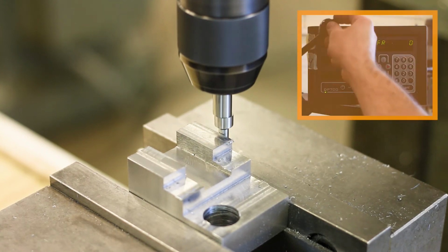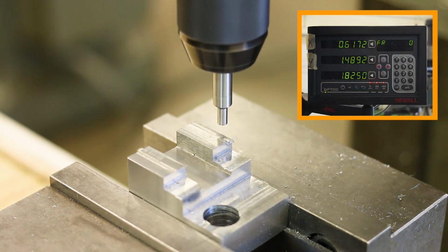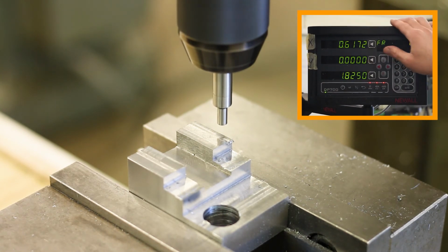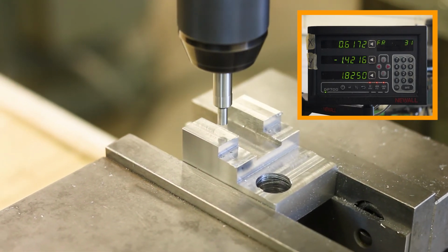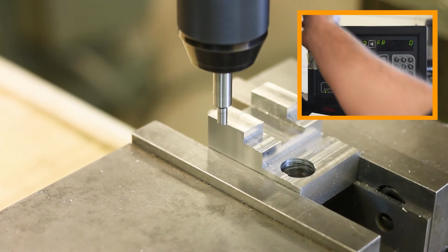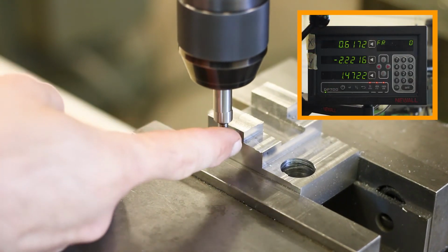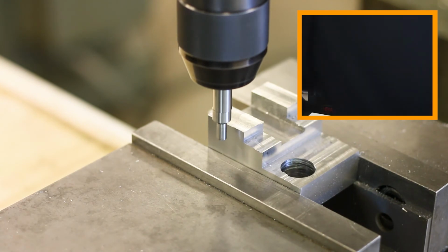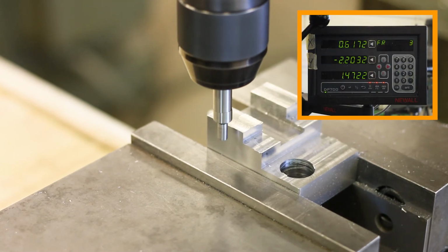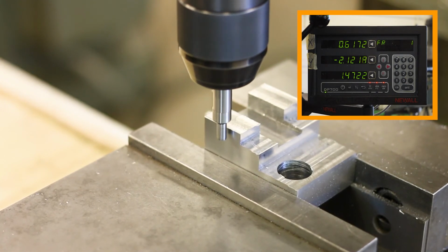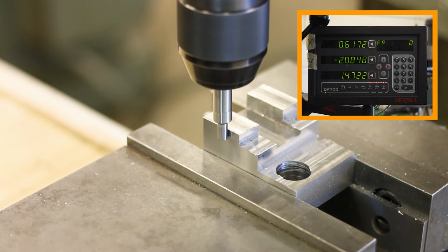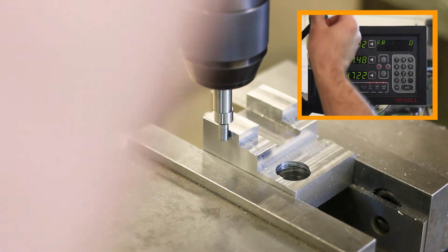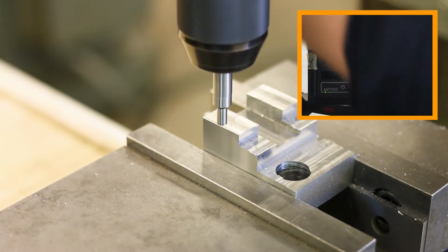Right there. Okay, raise that off of the part surface. Zero out the y-axis on the digital readout. Now let's go and do the same thing on the other side. And I'm going to spin this around the other way so that we can see it pop out a little bit better. All right, there we go. Okay, lift that off the part surface, turn it off.